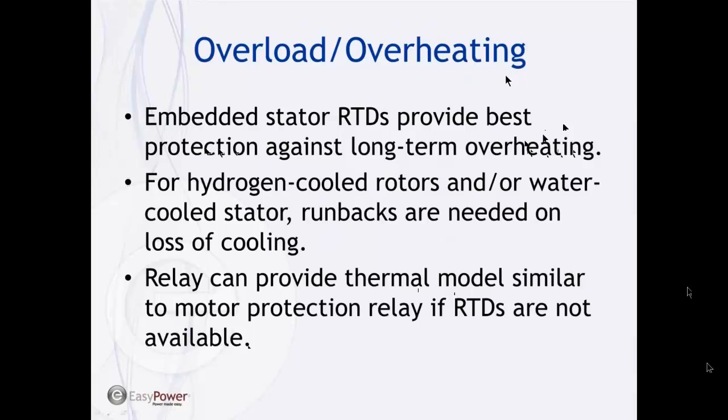Generator overloading or overheating, the best protection there is really going to be embedded RTDs, temperature detectors in the stator, and to provide alarm and tripping for those. And if you have water-cooled stator or hydrogen cooling, you're going to need some runbacks, automatic load reductions or trips if you lose those modes of cooling.